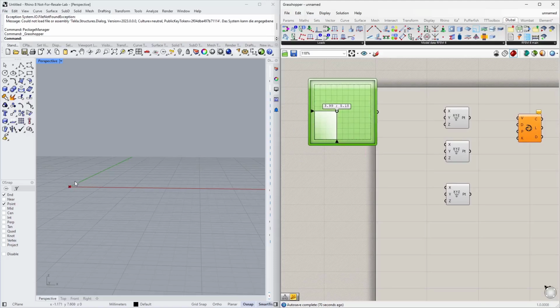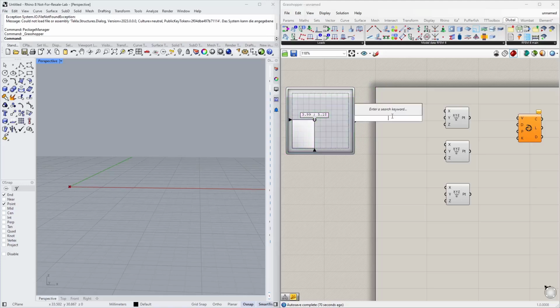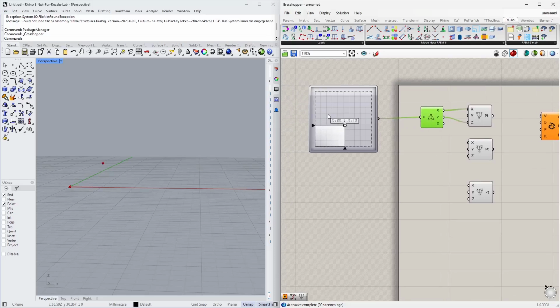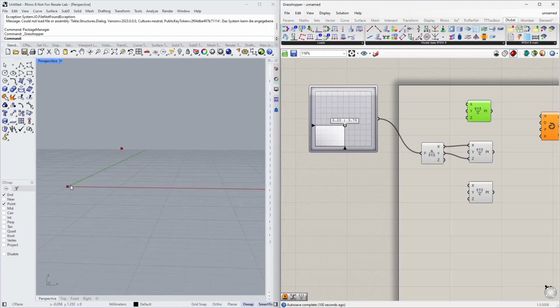Now my curve will be in the xz plane, therefore I need to deconstruct the node that I get here. So I deconstruct the node and I build it again just using different coordinates. So x should remain as the x coordinate. The y coordinate, which I can modify here, should be the z coordinate. So you can see now, actually that's already the second node, my bad. The first node should be at 0, 0, 0. So that's the first node here in the center of origin.